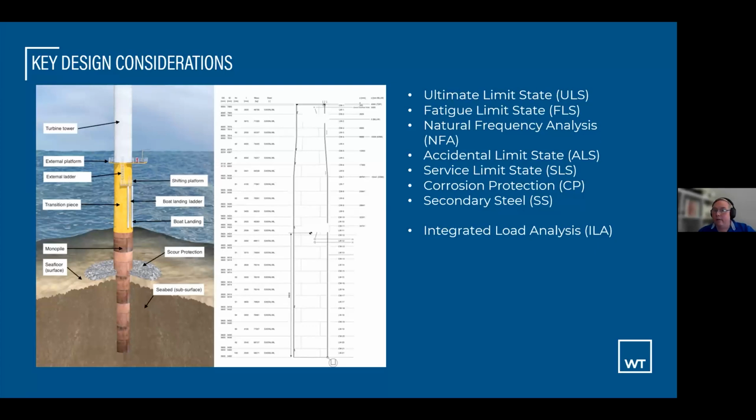As that soil liquefies, the subsea structure will be able to move. When the storm passes, the soil will then resettle under the pressure of the water above it, and you want to make sure that the position in which the turbine resettles is within a certain range, typically 1/4 of a degree either direction. And that's your service limit state.